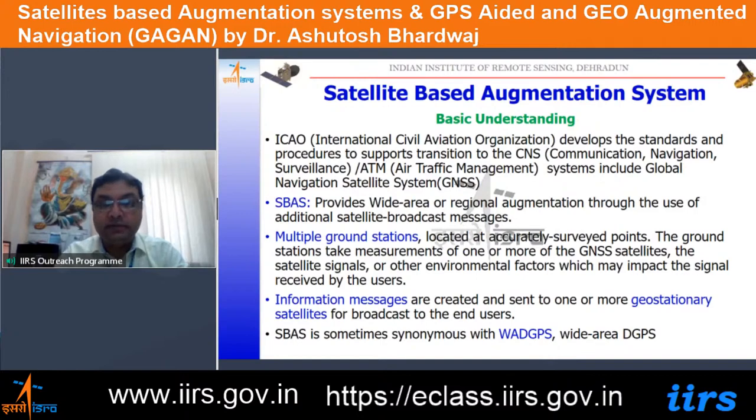What we have understood in the DGPS is that these stations basically act as the base stations and they generate the correction parameters for the operations nearing those specific stations. So the nearer to the station, the higher the accuracy we are going to get. And in this, geostationary satellites are also playing an important role, because these correction messages are sent to the geostationary orbit satellites and they broadcast the correction parameters to the user again. And all this is happening in real time.